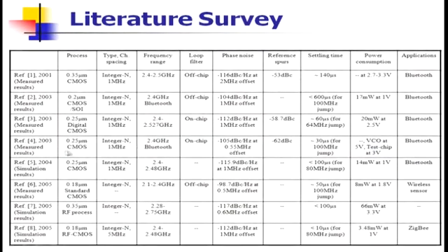You might recall my first VCO design, I showed you some kinks at the left and right side of the center frequency, at 5 megahertz spacing, our reference frequency. That is known as the spurs. And the spurs are very bad because they will cause some sort of intermodulation products, so you have to remove the spurs. 53 dBc is not a very good spur performance.